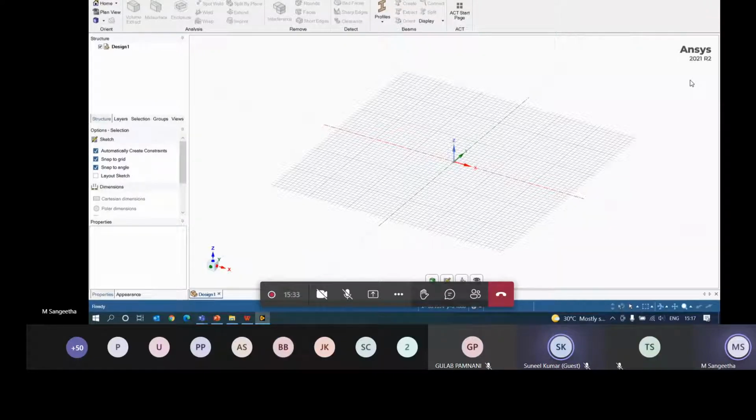Let's say your geometry gets converted into 2D, or initially it was 3D, and when you are importing it here, due to some data loss, it is getting converted into a surface body. So those problems have to be rectified, and you have to modify them and get the actual geometry. In that case, your repair and prepare tab will play an important role.